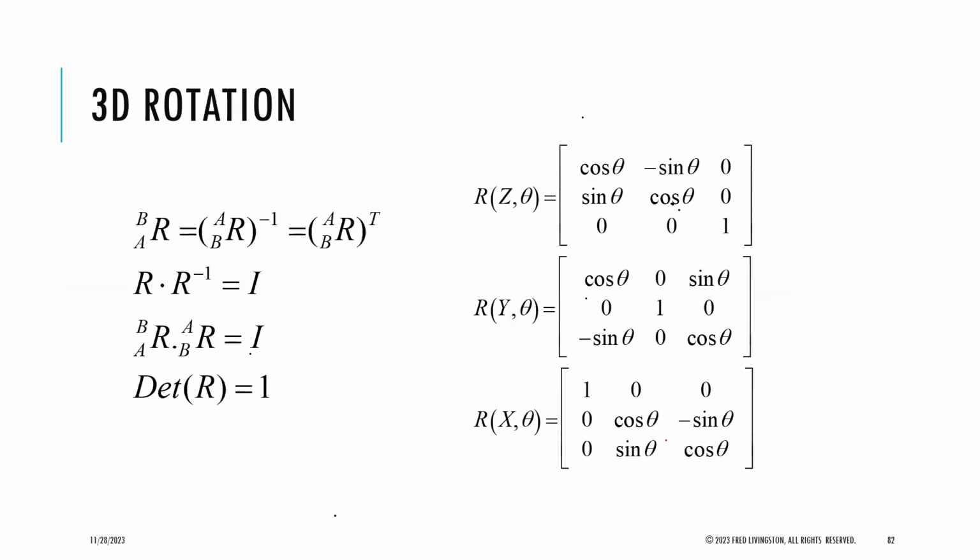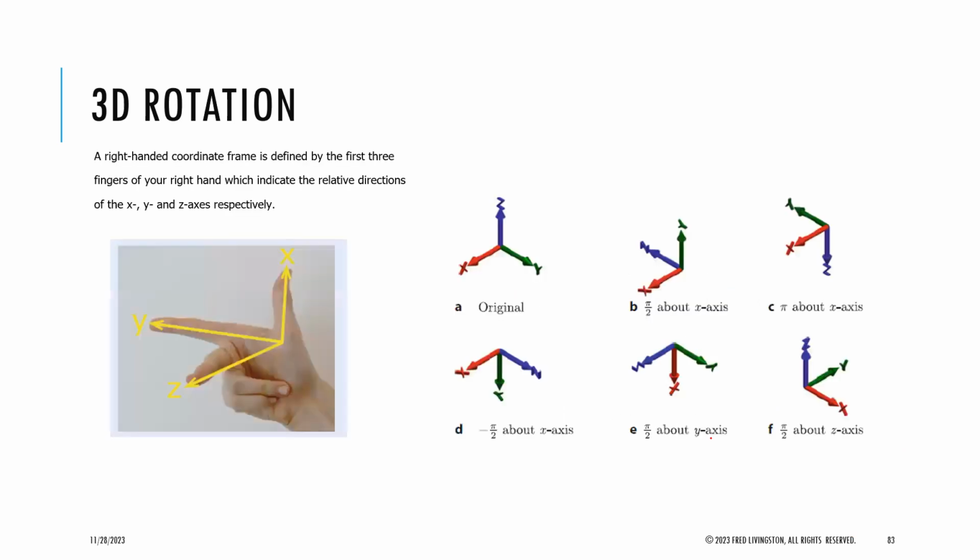And so this is already the generic rotation matrix of a system. They always use the right-hand rule in robotics in general, I've never seen a left-hand system. And so for a positive rotation, you put your thumb along the axis of interest and then you curl your fingers, and that gives you the positive direction.